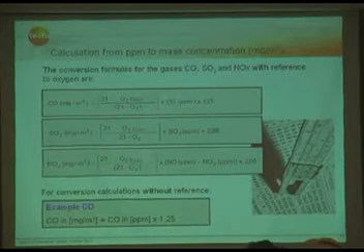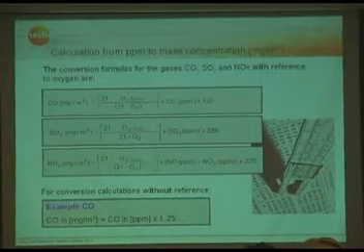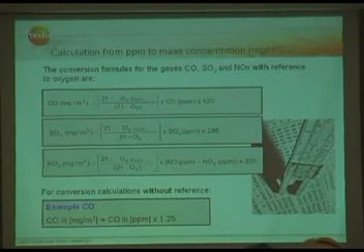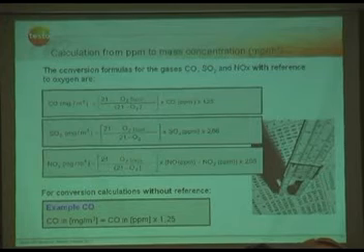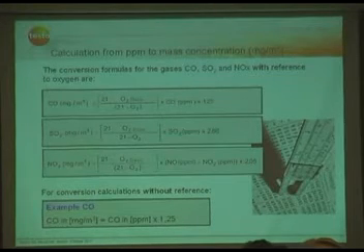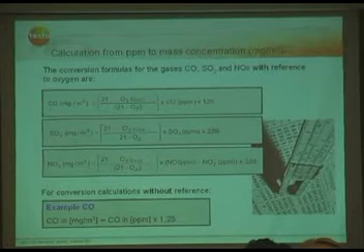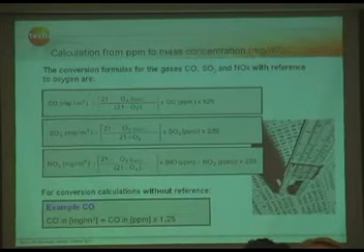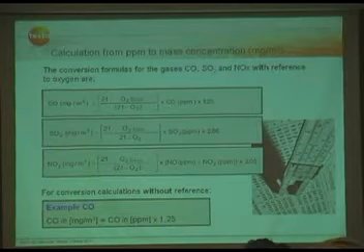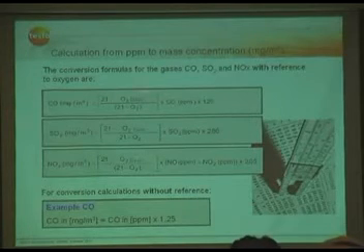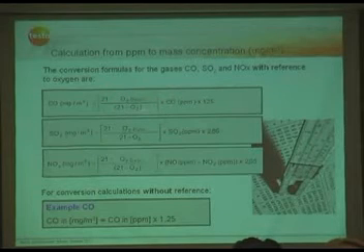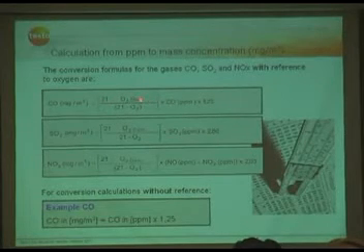And this really depends on the application, because every application has its O2 base. That means just to make sure you can compare readings of different applications, because some applications have excess air, some have reduced air, and you cannot really compare the emission values. Therefore, the government requires the O2 basis for different applications.